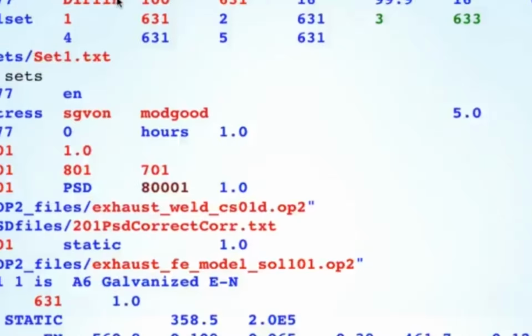We're using something called Dirlik, which is the most common method for your kind of models, I would say. It defines how the rainflow count will be created from the response stress data. 100 is a filtering number. That number can be 100 or less. If it's set to 100, then the whole model gets analyzed. Anything less means that elements with very low stresses get reduced from the output, so that can be set to a smaller number to reduce your output file sizes.